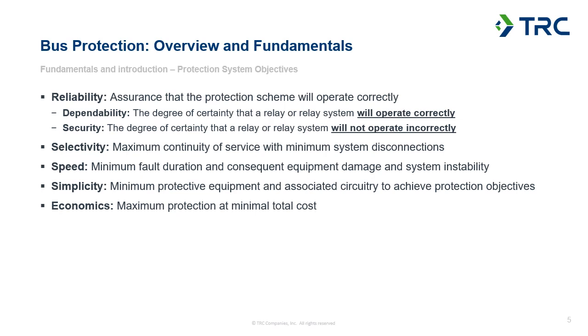Simplicity also comes into play here, as with any, ideally you're going to provide a bus protection scheme that's straightforward and easy to maintain. They can get a little more complex, where you may be looking at multiple sets of currents, and you need to make sure your current transformer connections and your tripping operation and things like that are all happening, because they do interface with more portions of the power system breakers and things like that. Trying to keep it as simple as possible is always a good approach.